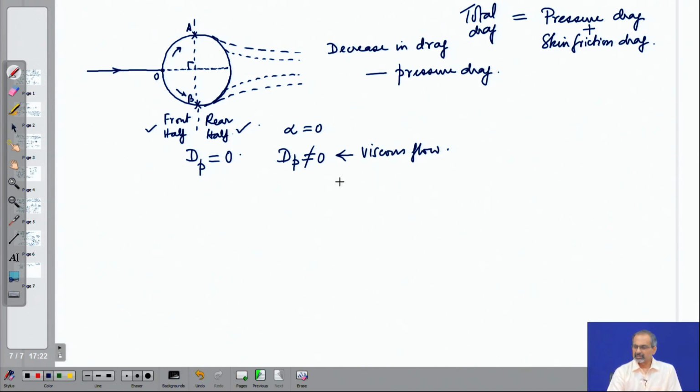So, if pressure drag is important for bluff bodies, you can reduce that and thereby reduce the total drag significantly if the flow is turbulent. On the contrary, if it was a streamlined body like an airfoil, this airfoil will have a very thin wake, especially at low angles of attack. Thus, pressure drag is not the dominant drag.